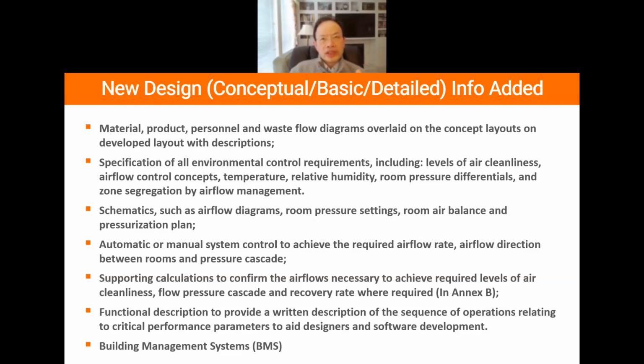In some design documents, especially for the pharmaceutical industry, recovery time needs to be considered as a part of the design and eventually tested per the dash 3 standard, to see how long it is going to take that room to recover to the original previous level.